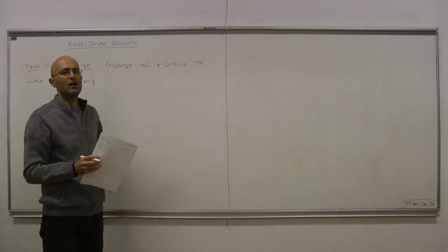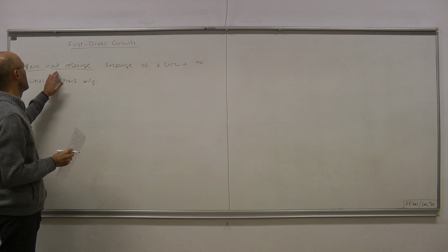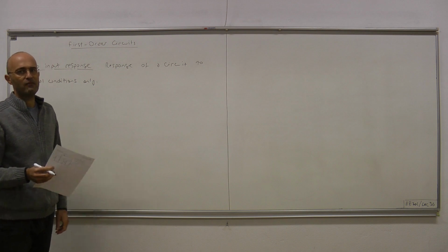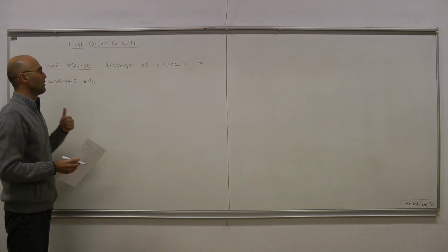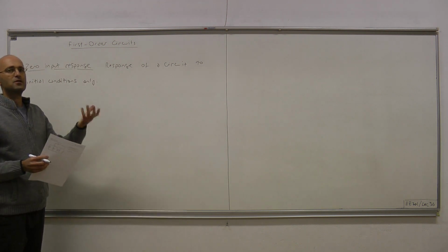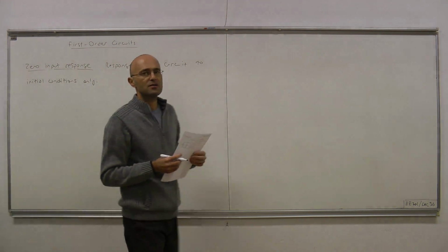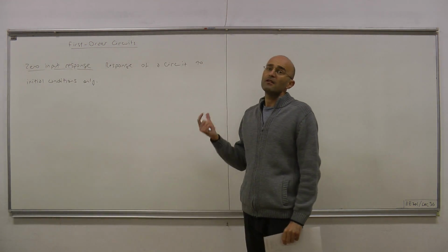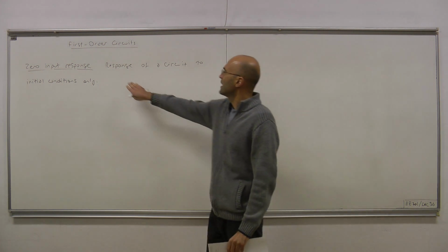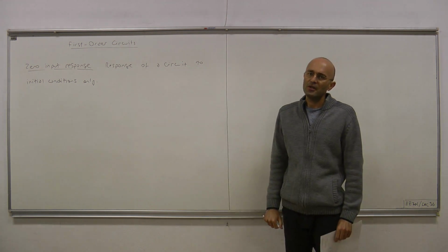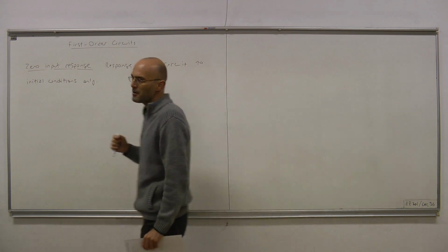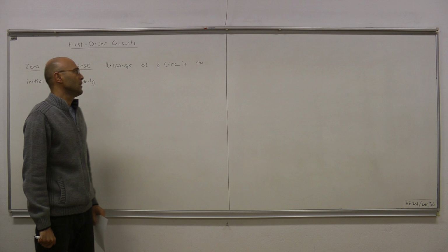Note that for an LTI resistive circuit, if you have no input in the circuit, then there's nothing to solve. Everything is zero, every voltage and every current. However, with dynamic circuits, that's not the case. Even if the external inputs are zero, that is, the voltages from independent voltage sources or the currents from independent current sources are all zero, we still have a meaningful, non-zero response, and the reason is the initial stored energy contained in our dynamic components, the capacitor or the inductor.